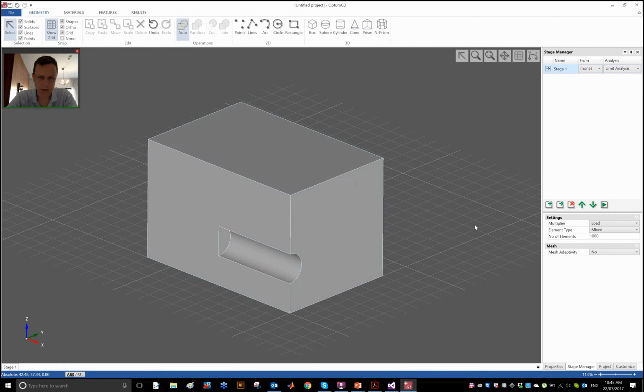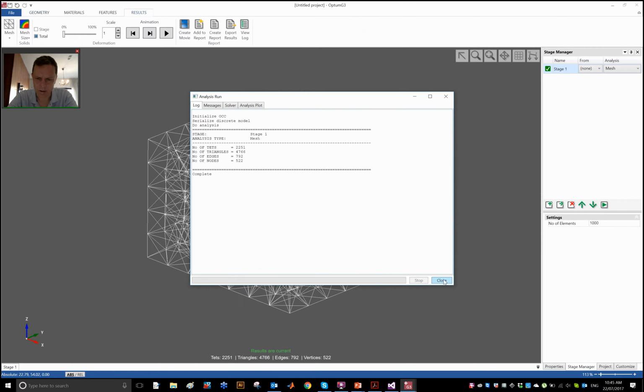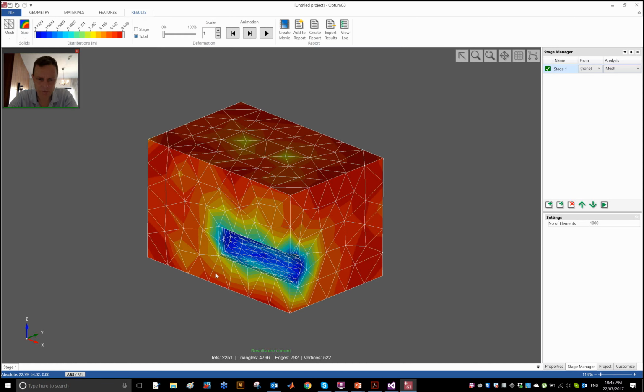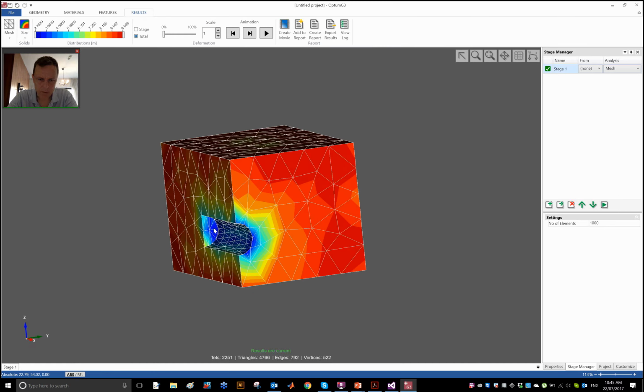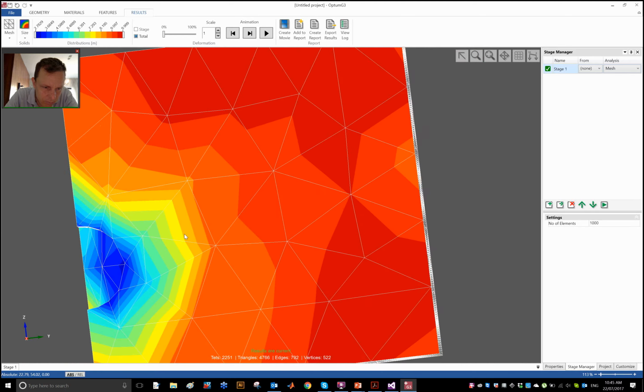But before I actually start applying material and boundary conditions and so forth, I want to just have a look at the mesh that I get, because it's always a bit dicey how, especially the base of these cylinders, will be discretized, also the rest of the cylinders, because there will be an approximation. It's just a good idea to have a look at that, because it is not too critical in this case, but we want a fairly nice approximation of this circular tunnel. And do we get that here?